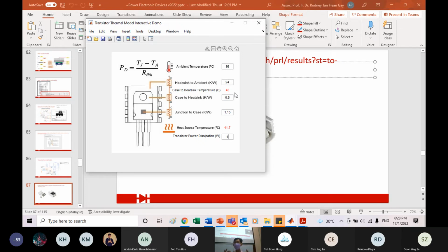You see, in the past in electronics, your transistor is either on or off. That's all. Base, collector, emitter. That's it, end of story. You think you know everything about electronics already? No. So in power electronics, I bring you further to show that a transistor is not just simply on and off. It has important characteristics that you need to understand from the data sheet. At the same time, the switching frequency does affect the power losses, and these power losses all the while we just think of as power loss, but they convert into heat. So I move further again to how to deal with this heat.